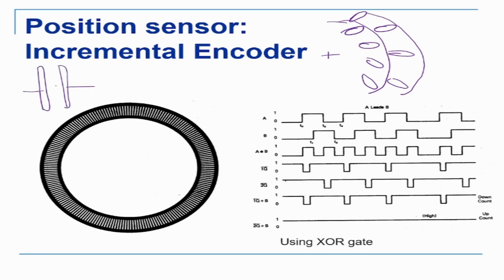And what we are seeing is that when it is rotating, there is a slight shift in between them. So the holes are not aligned. So when encoder A is giving a signal, which is shown here, this is my high and then low. These are square waveforms. There is a slight shift in here. As you can see, there is a small shift there. So signal B will come a little bit after some time. Why? Because there is a shift in between the two encoders, right?